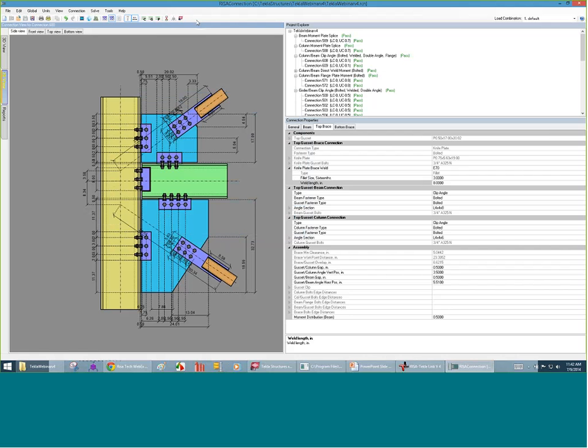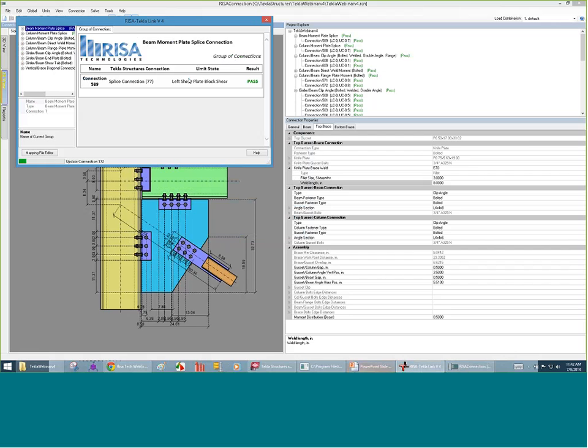One of the other pieces is that once we get over to the Tekla Structures model, we have another summary there, so that's a great way to see the summary of what happened over here as well. I'm going to click this button that says Export Connection Results to Tekla, and it's going to send that directly back over. It's opening the summary sheet we saw on the way back from Tekla Structures over to RISA Connection, where we saw it put all the information in here. What it's doing right now is laying out the results of this information. It's laying out the pass and the fail. It's telling the program in Tekla Structures what passed and failed.